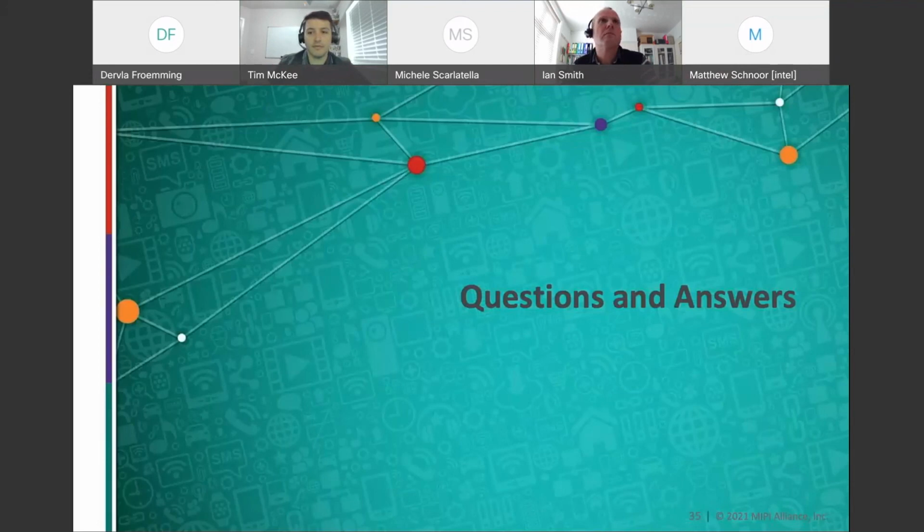Right. And one more point on that, that's another reason why a lot of I3C controllers are recommended to start off their transactions with start 7E, then repeated start, and then the address of the target they want to talk to, versus just start and then the address, because that actually helps to continually signal to such devices, you're on an I3C bus, by the way. It just continues to reinforce that.